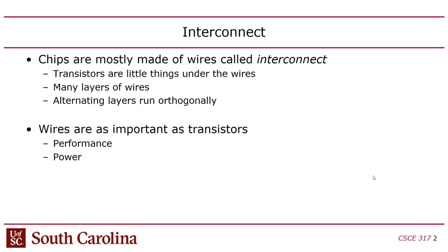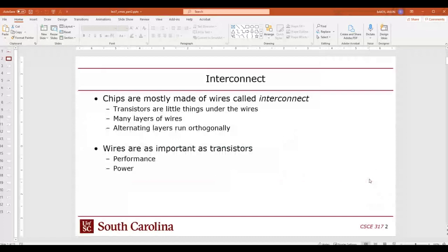Okay, so last time we were talking about interconnect. We talked about how delay in integrated circuits is determined by capacitance and resistance, and delay is also what determines performance ultimately. I mentioned that you get delay from the logic gates, and you also get delay from wires. And so in the first part of the lecture, we talked about delay in capacitance and resistance in logic gates. And in this part of the lecture, we're talking about the capacitance and resistance in wires, or interconnect.